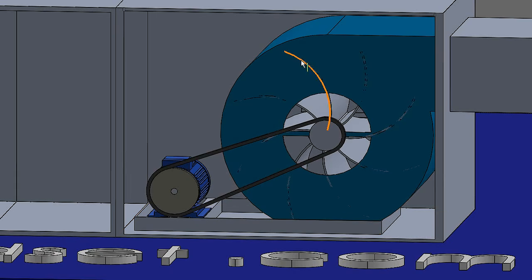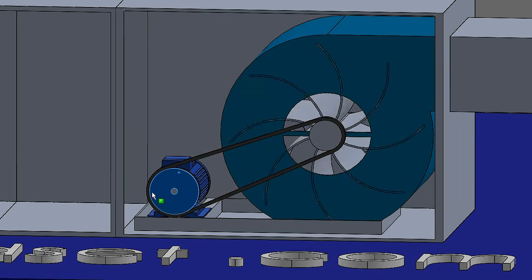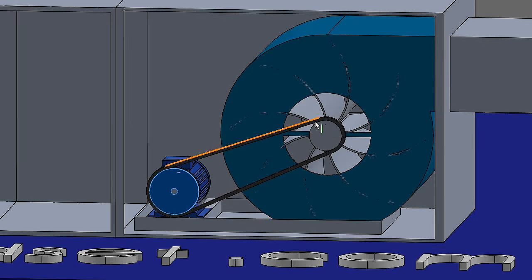You'll notice that this fan here has backwards curved fans. There are a lot of different designs you can have. This is fairly efficient. There's a new type of fan out which is actually much more efficient than this, but I like this one just because you can really visualize what's happening there, and I have coupled these so that as we rotate the motor, you'll see there that rotation is being transferred through the belt. The belt is then driving that pulley, and the pulley is then driving the fan there, driving the fan blades.